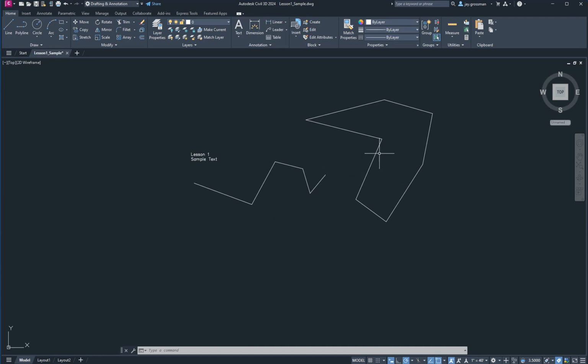If you now click on anything you drew before, now you've got these little blue boxes. We call those grips. And so those will pop up. And so now you can do dynamic editing of these elements that you just drew, and I can move stuff around. I can grab those grips and move them around. I can snap them onto each other, that kind of stuff. If you click on it now, you've made your elements editable and you can do things with them. So that was the next piece, is clicking on things and seeing what happens. In the menu bar down at the bottom, it says try turning on ortho mode or turning it off.